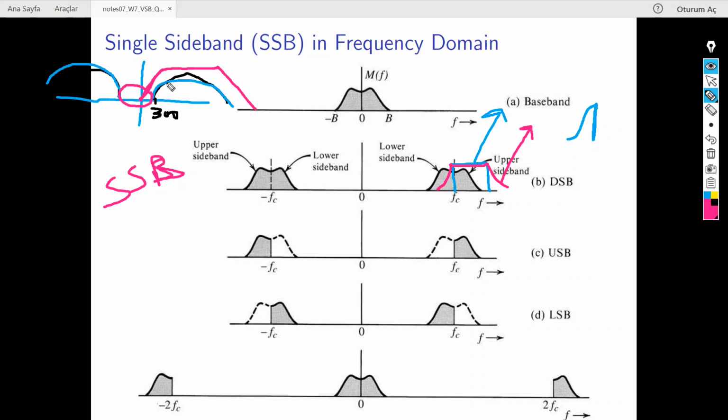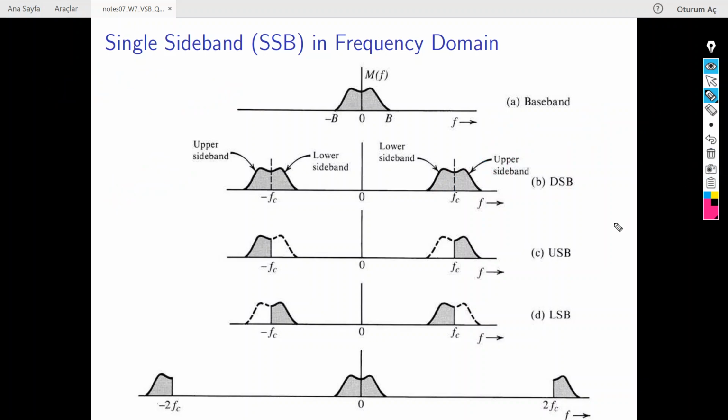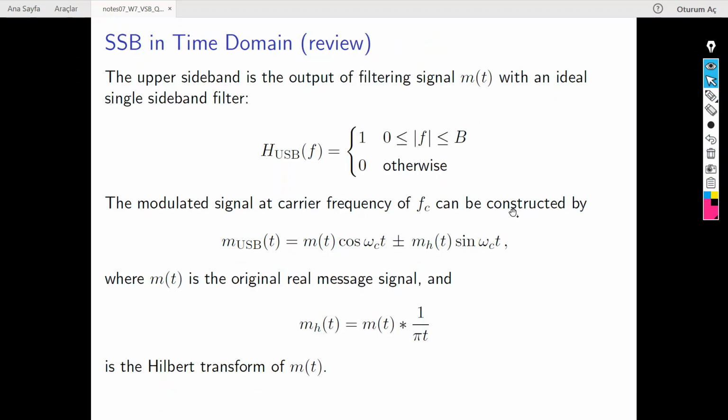Now, when you want to transmit video or images or any other types of signals that have low frequency components, what do you need to do here? You need to use vestigial sideband modulation. This is the reason why we use vestigial sideband modulation. Now, this is the basic introduction to vestigial sideband modulation, but let us now get into the details of the derivation and the block diagram of this type of modulation.